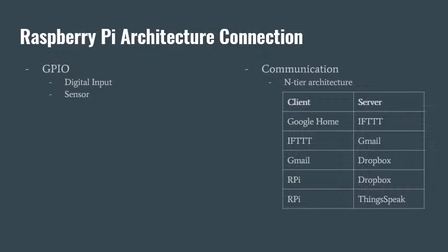Since Raspberry Pi is based on SoC, which stands for System on Chip, it doesn't really fit the definition of South Bridge or North Bridge. Some peripherals are directly addressable by the CPU. Other peripherals such as Ethernet, USB hub, power management, or GPIO expander are addressed over the relevant peripheral buses.